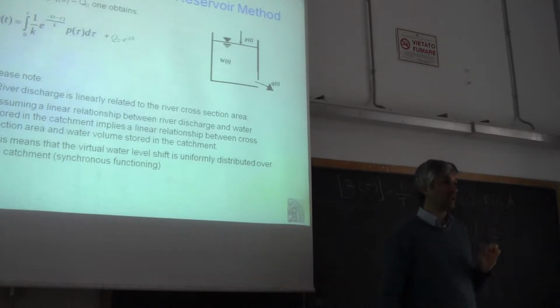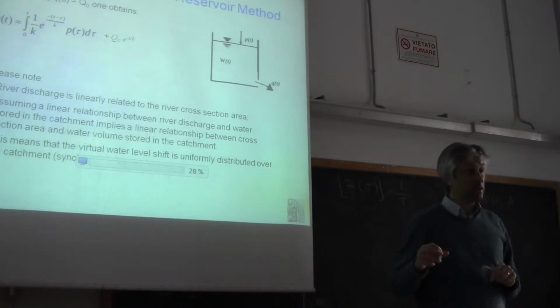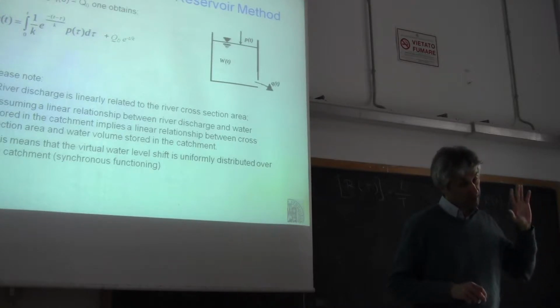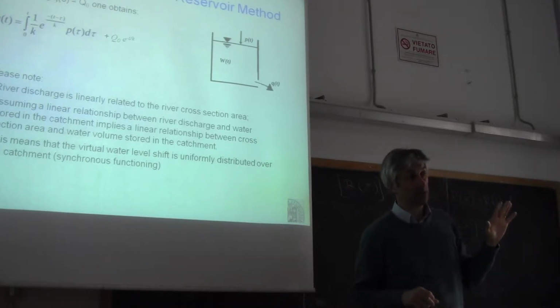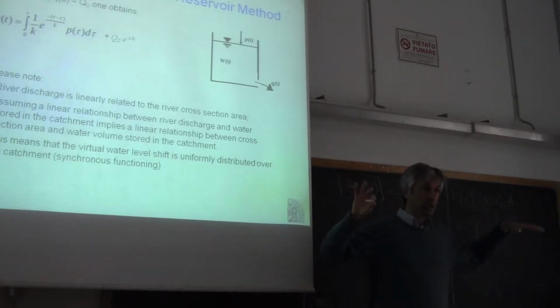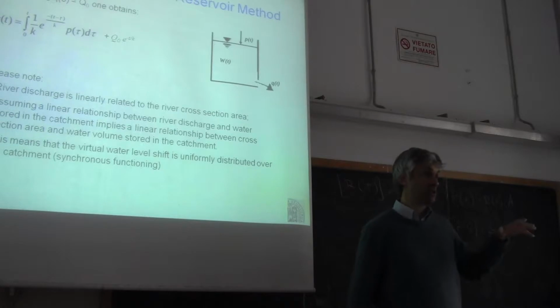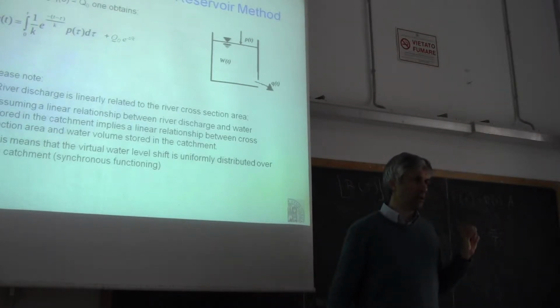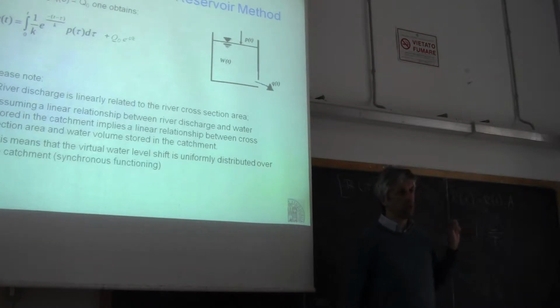This is indeed a challenging task in hydrology, and if you have several rain gauges over the catchment, the task is simpler, and you can perform a spatial interpolation, but still the estimate is uncertain, because rainfall is spatially variable. At a given time t, rainfall is spatially variable. So if you have only point measurements and you estimate the average rainfall over the catchment as the average, for instance, of these point estimates, there is uncertainty. And this is, as I said, a typical question of hydrology, how to estimate the average rainfall over a catchment.